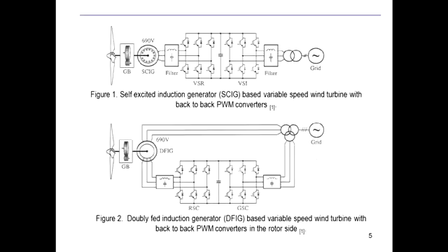So, this is still in the stator, but using this capacitor, which is for storing the energy, and some of this capacitive energy, one can allow this induction machine to self-excite, all right? Induction machines don't have any excitation in the rotor. There is no inherent magnetic field, so it cannot generate, okay? But if you can supply this machine with a flux-producing current in the rotor, so that a field is established, then the machine will generate, okay? So we will be looking into that as well.